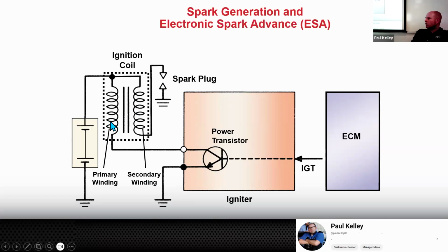So if you had a coil that didn't work, you could make sure the coil has 12 volts. Then you have to go over to the triggering and see, is it getting a pulse? The pulse is going to be ground, no ground, ground, no ground. If you had a test light, you should see a flicker right there. Or if you had a meter, you should see a voltage jumping. But the best way to do it is probably to use an oscilloscope, and you can graph that and see what the transistors do. The transistors opening and closing, that's their job. Make sense?